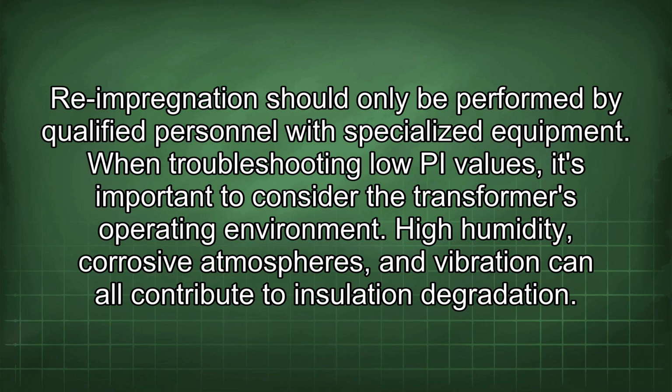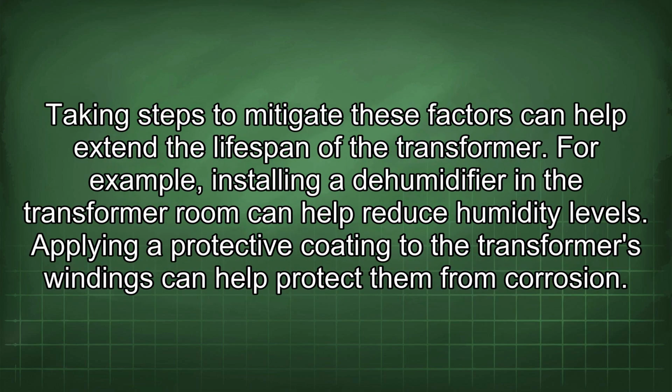When troubleshooting low PI values, it's important to consider the transformer's operating environment. High humidity, corrosive atmospheres, and vibration can all contribute to insulation degradation. Taking steps to mitigate these factors can help extend the lifespan of the transformer.